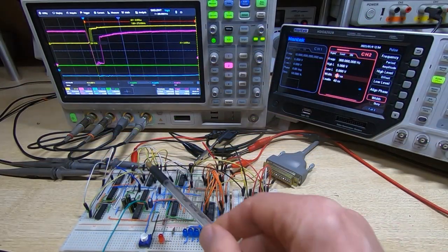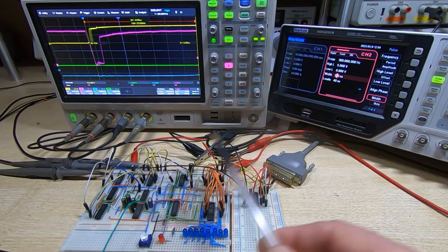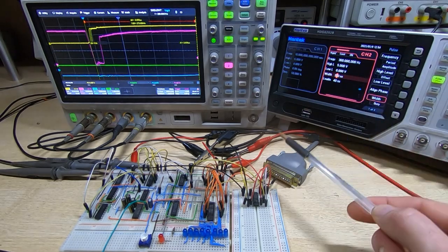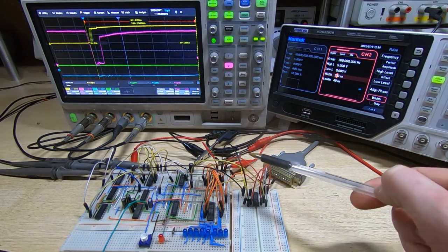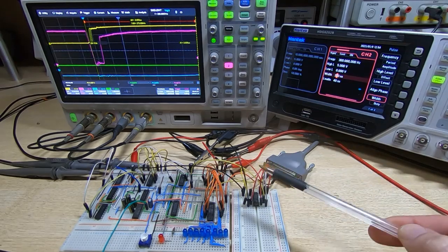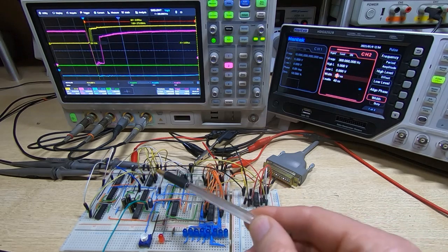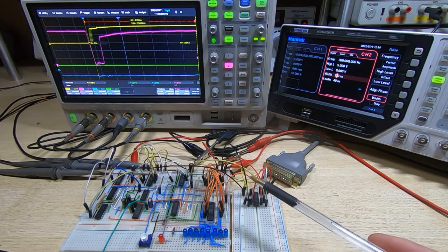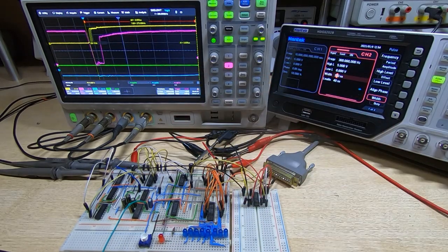Okay, we've got the circuits set up, we've got the transmitter set, and we're driving it with our 300 nanosecond start pulse. It's got the 10 megahertz main clock going into this circuit, but as I said, this is normally part of our main board, and then the 625 kilohertz circuit is being used as the primary clock for the two counters, one for transmit, one for receive, and the 10 megahertz clock is being used to make sure we get proper operation of the counters.